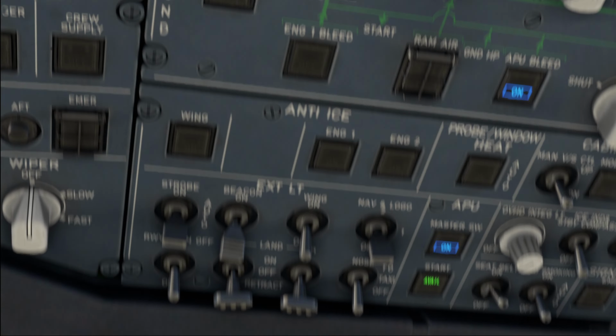Finally, you will notice that there is also a high position available on here in the A319 and A320 as well as the A330, which does not exist on the A321. Now, the background of this position is that a high pack flow might be needed in case you've got especially hot or humid conditions where normal airflow is not sufficient to cool the cabin sufficiently.